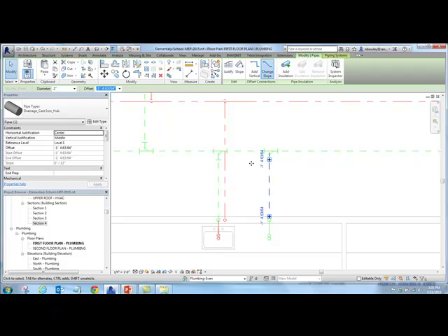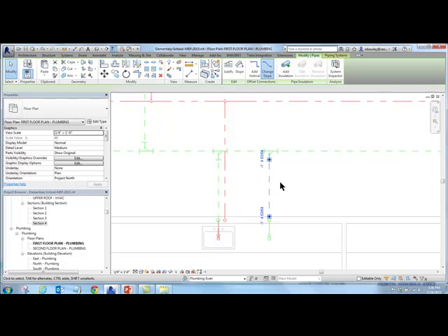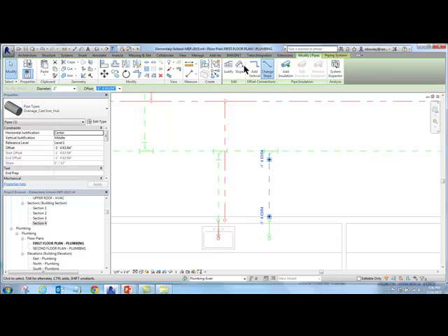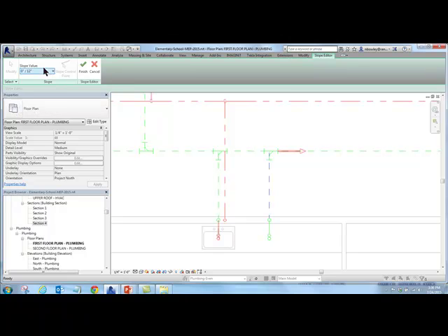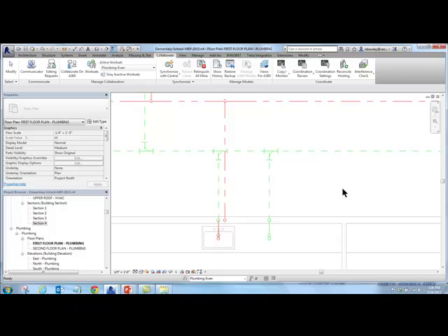It's not giving me my slope options. Yeah, might be something with connecting to the projector. So when I hit change slope, it's supposed to allow me to change the slope, but usually it lets me do it after the fact. Oh, there it is, right there, the slope button. That's what I was missing. And then I change it to 1/8 of an inch, and now it's sloped down to the main.